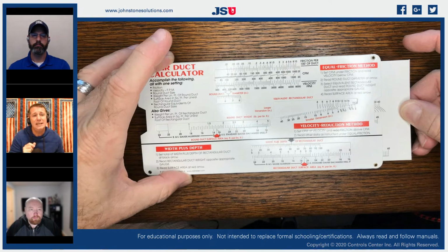But what we're seeing in the industry is that as our equipment gets more efficient, the static drop across our equipment is starting to increase. If we looked at a coil, we talked about this just a few weeks ago. If we talked about an A coil from the 1990s, a 10 SEER or so, we typically had about 0.1 inches of static drop across that coil. Now, because we're trying to shorten these coils to fit in our shorter applications, we're adding a lot of resistance across our coils, and we're now looking at higher filtration than we looked at 20 years ago.